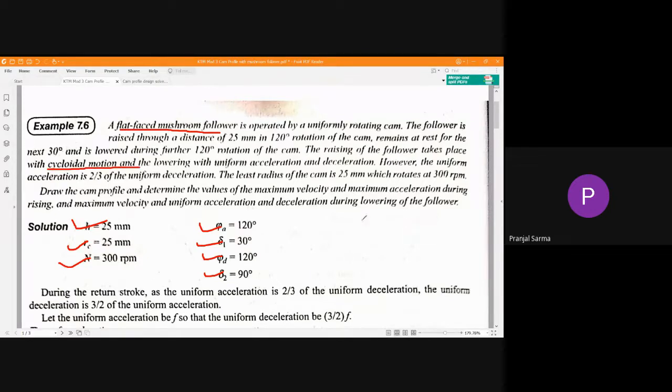So there are two basic stages. First step is drawing the displacement diagram properly, considering proper scale, proper motion profile, etc. And the second step is considering kinematic inversion, you have to draw the cam profile for that particular type of cam and follower arrangement. It might be offset type or it might be inline type. Depending on the question, whatever is being said, that way you try to draw. If nothing is said about offset, then automatically you consider radial or inline type of cam and follower arrangement.